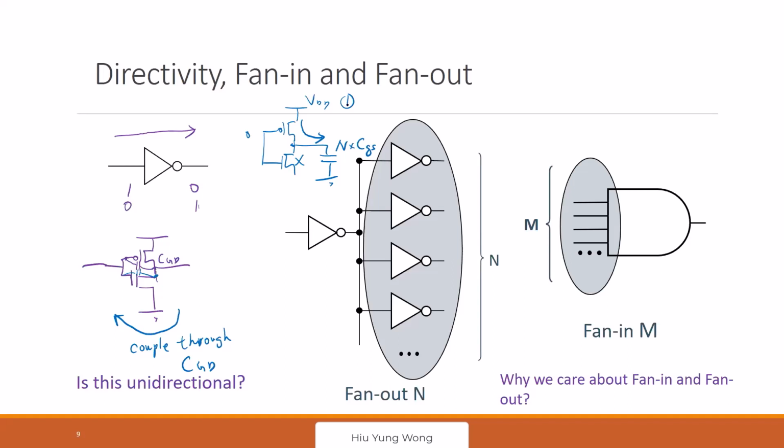If you see even deeper, this guy itself is also a resistor. It's not a perfect current source, right? So ID set limiter, right? And then the PMOS has a resistor, RP. So then you have an RC delay, right?